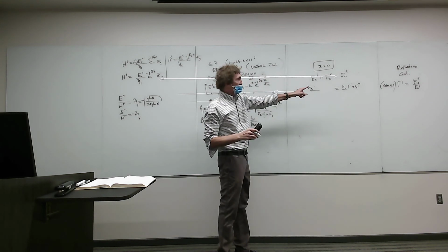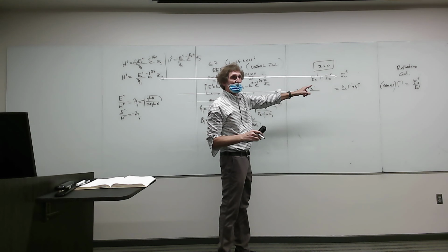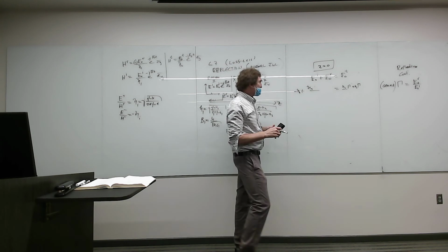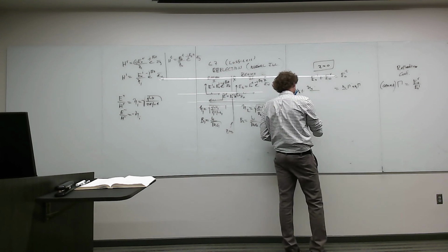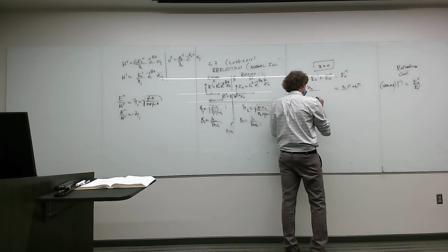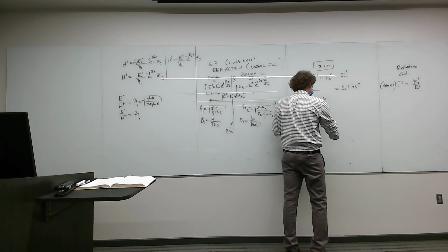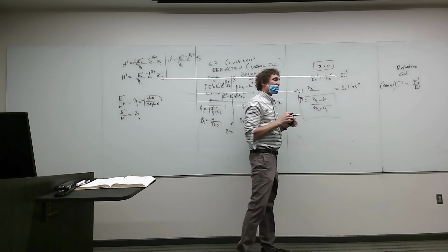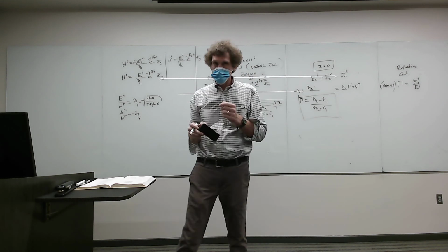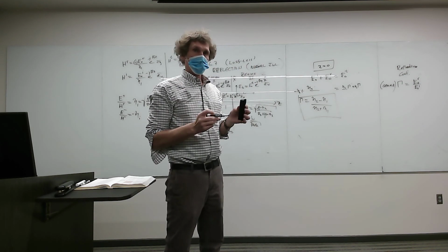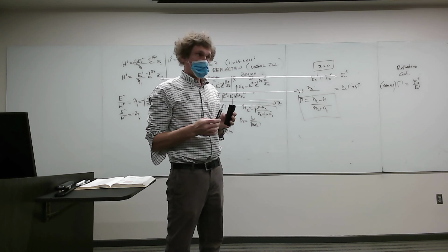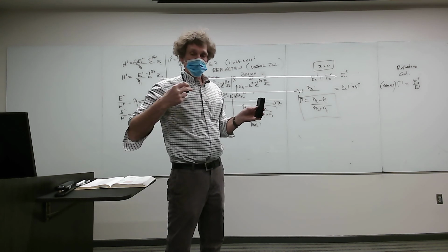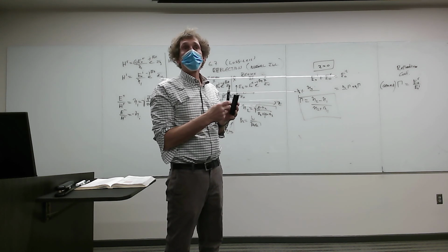And then I factor out eta 2 there, and I divide by the coefficient. So what I'm left with is gamma is equal to eta 2 minus eta 1 over eta 2 plus eta 1. That's the reflection coefficient for a normally incident wave on two planar surfaces for a propagating wave. The surfaces are planar, and it's normally incident. By the way, this is a very useful equation.